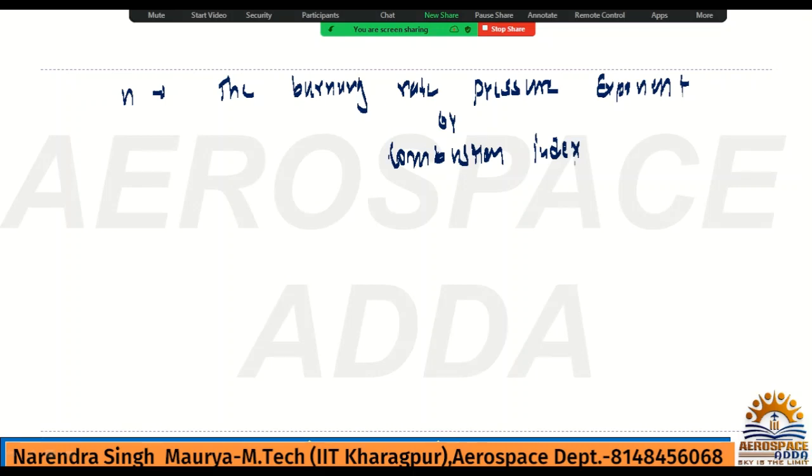It is independent of initial grain temperature. I told you initial temperature is constant, so obviously it will be independent, okay? And the effect of chamber pressure on the burning rate depends on the constituents of the propellant, okay? So basically whatever formula you got is for constant temperature. That's the meaning of it.